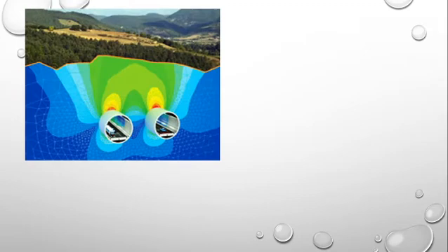However, when designing the size, thickness, and how they're attached to the wall itself, the engineer would have to do some kind of finite element analysis. We've got here a little indication. It's not the Channel Tunnel, but it's something similar. We can see from the colours used in that simulation where we think the greatest stress is going to be. As expected in this one, it's at the very top wall of the tunnel. So the engineers, when deciding the number, thickness and attachment method for the segments, would have to consider all of these different pressures.